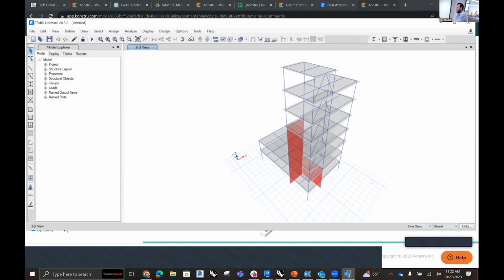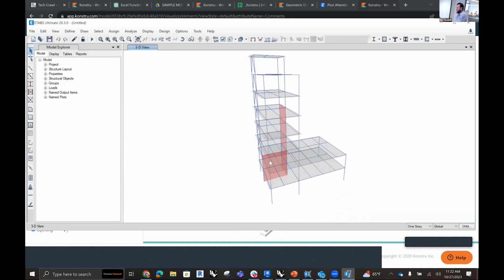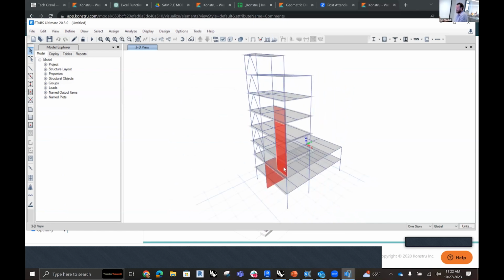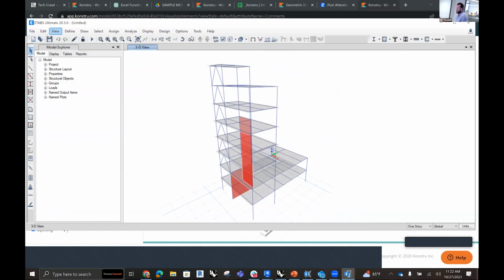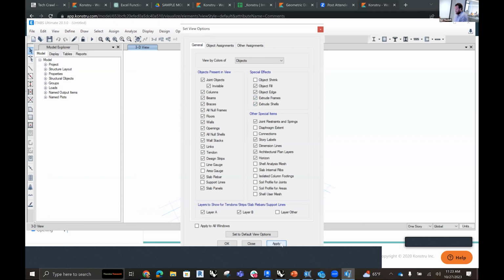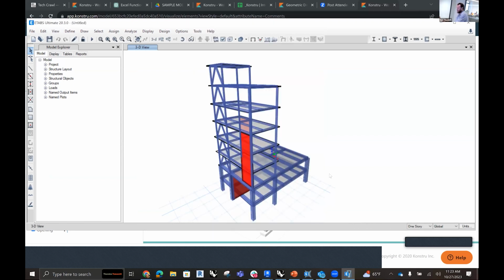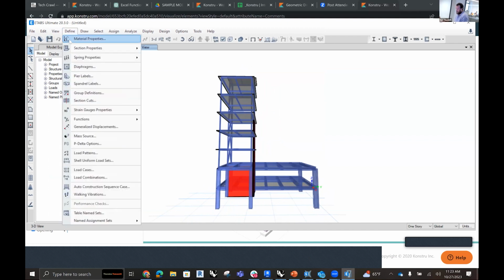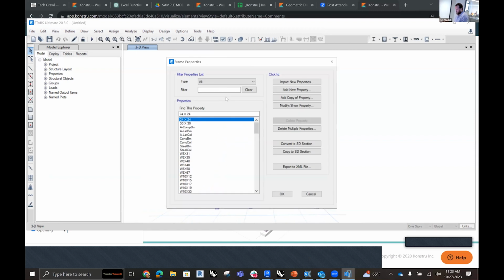There is our one-way translation from our Revit file across to ETABS. You'll notice that our geometry is all nicely connected and repaired as we made those changes inside of the Revit file first. At the same time, just to point out that we did capture all those properties and recreated them appropriately in ETABS. So we have all of our concrete properties on the bottom, all of our steel properties for the objects above. And it is worth looking inside of here to check out the frame sections. You'll see that Konstru created a new frame section called 24 by 24 that did not exist in ETABS previously.